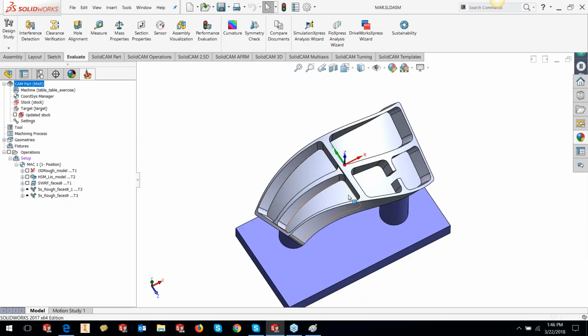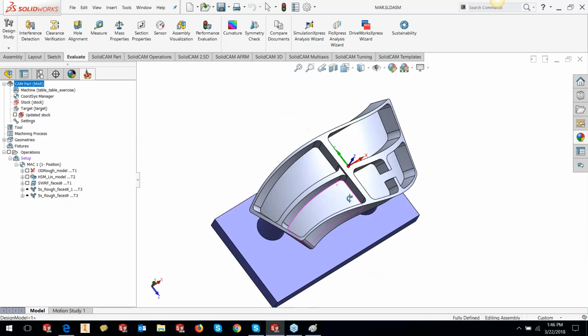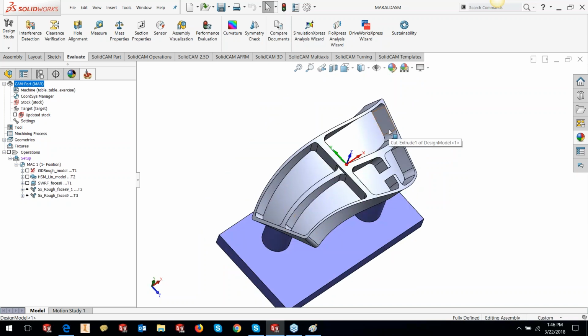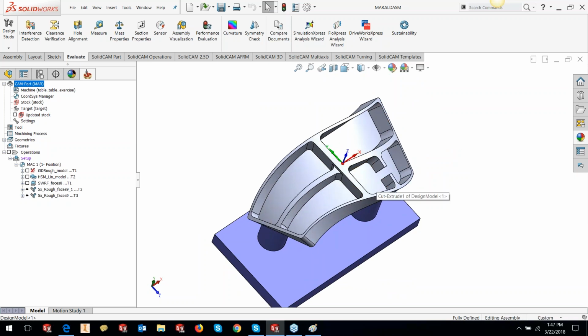If you would like to scoop out these pockets, there are several ways to do it. One is to create several positions and then do 3+2 indexing machining to scoop out the pocket. The other way is to use a technique called multi-axis roughing. Multi-axis roughing as a term is slightly deceiving, because we expect that we could give any shape to the software and it will rough it out. Actually, no, it doesn't work that way.